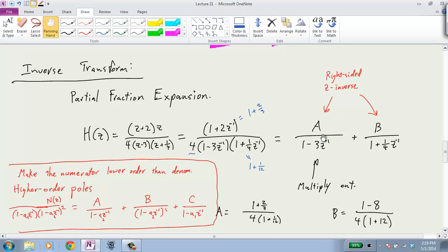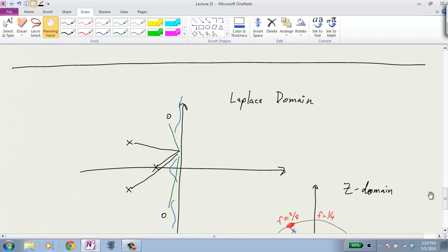And each of these you'll invert into a separate time domain signal. So if we can interpret a pole very quickly as a time domain signal, then we know that, for example, the impulse response of this system will have the time domain properties of these 3 poles because it will have 3 different terms, each with one of these poles.